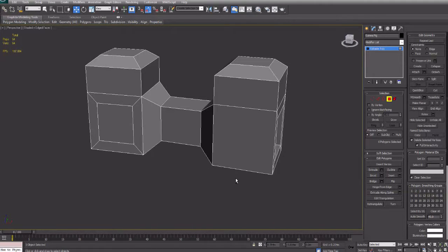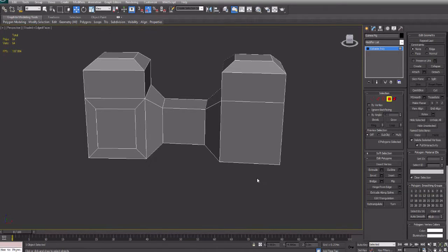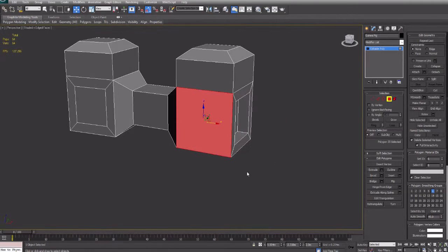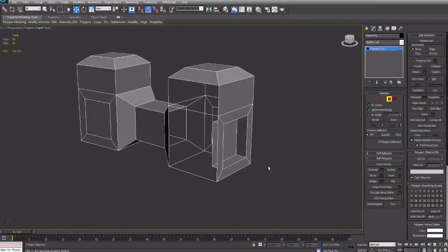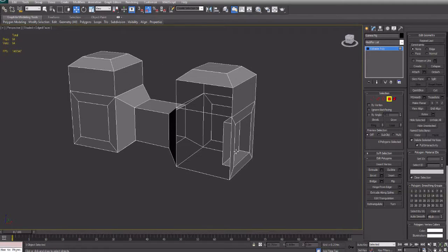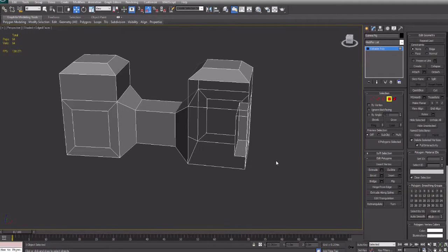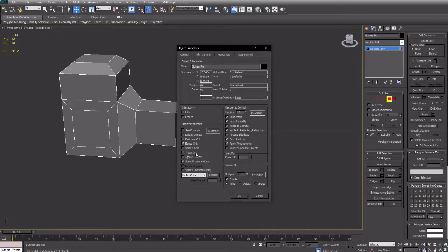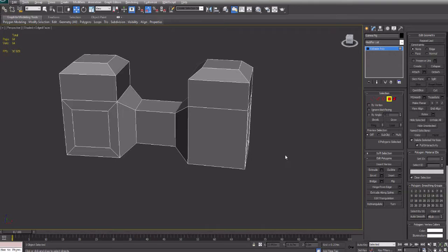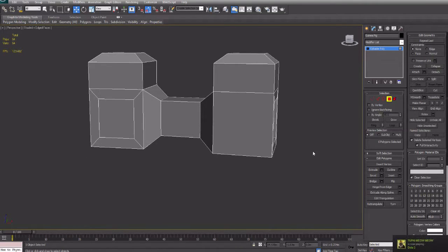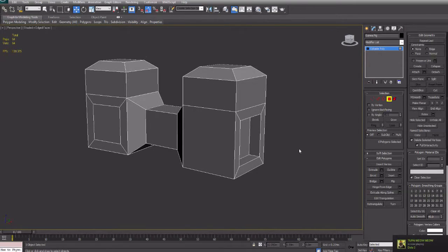Okay. So flip. You use this if you want to flip the normals, or basically if you want to reverse this one, you use flip. It's actually reversed. You can't really see the back face because I set it to back face culling. So everything facing the wrong side or wrong face is going to be invisible. So if you don't see anything, the normals must be flipped.